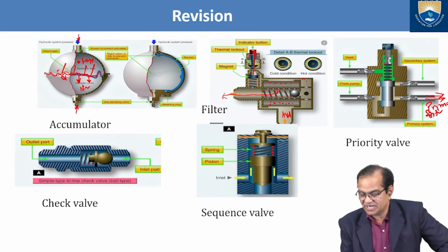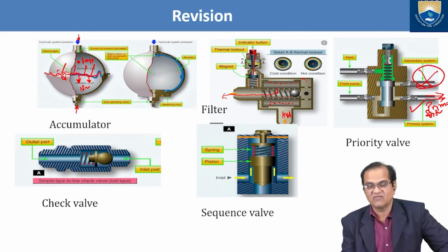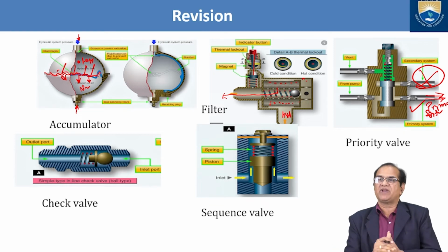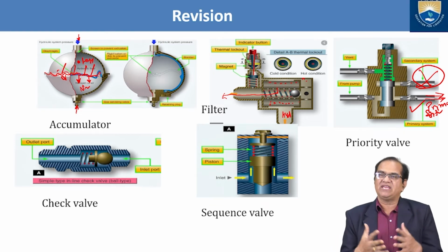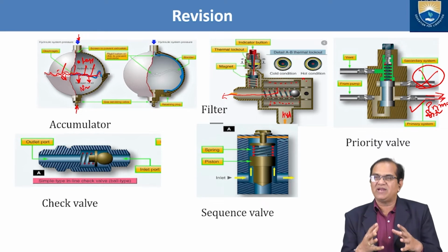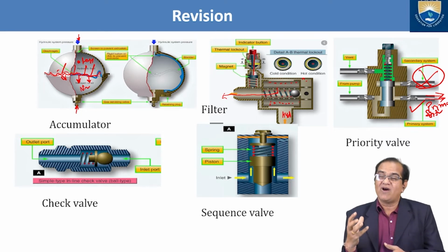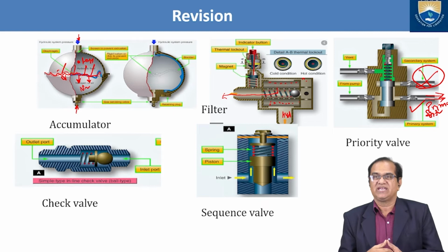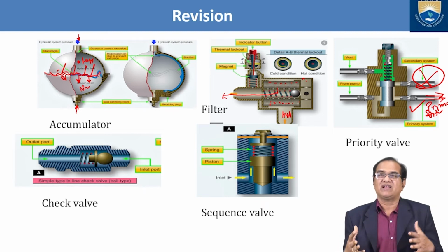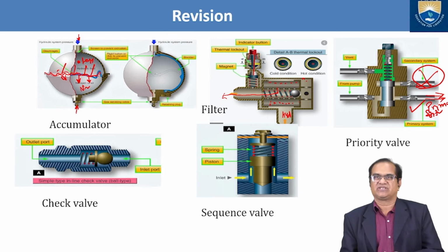Primary system. So in case the pressure is not sufficient, this system will be off and only this system will work. So this is the function of the priority valve. This will give the supply of the hydraulic fluid of a given pressure to the required emergency systems only, in case the pressure and the amount of fluid is not available in the system.